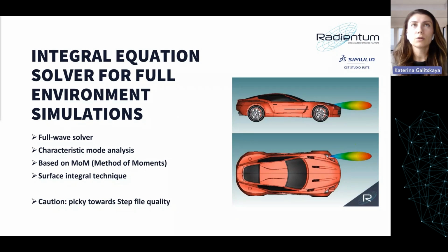On the next slide, we can see the integral equation solver. This is another solver for electrically large models, and this is already a 3D full wave solver, based on the method of moments technique. The integral equation solver uses a surface integral technique, which makes it much more efficient than full volume methods when simulating large models with a lot of metal and a lot of empty space. It includes a characteristic mode analysis feature, which can calculate the modes that are supported by a structure.